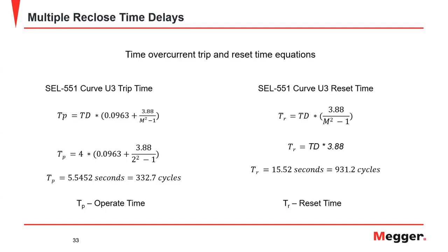Well, that's a very smart question, because it's someone who knows that there are reclosers out there that are not dependent only on the amount of current, even though the recloser operation is mainly done because of the amount of current that we have in the system. A lot of reclosers out there use voltages from both the line and the load sides in order to do some sort of automation.